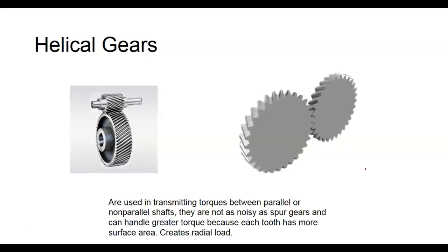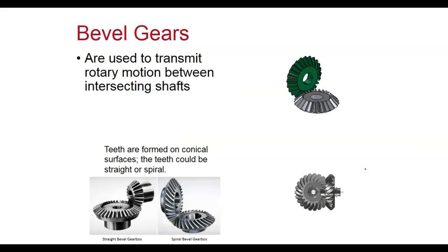So saying which one's the big and which one's the little depends on whether it's a torque multiplier or torque divider. For a torque multiplier, the output is going to run slower than the input. For a torque divider, the output is going to run faster. And this is true on just about all our drives, whether they're belt drives or gear drives. We measure output over input, right?